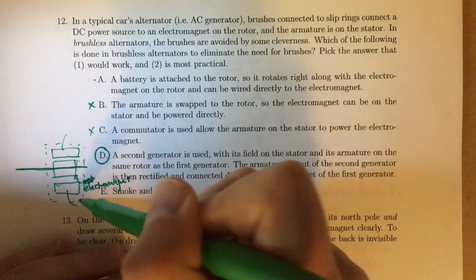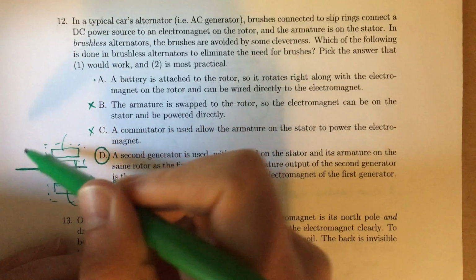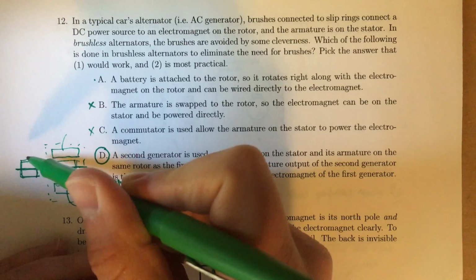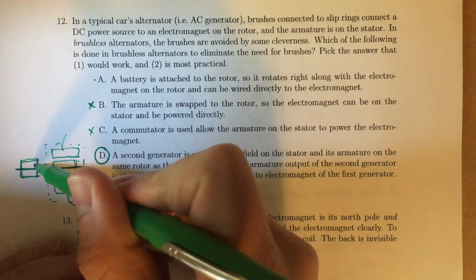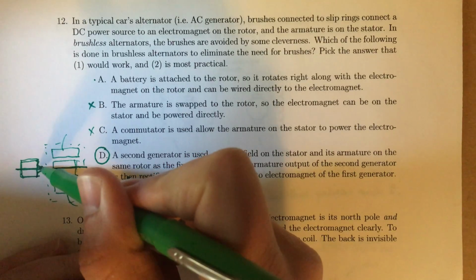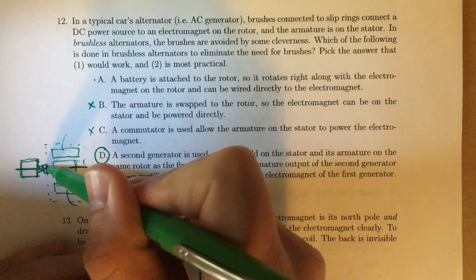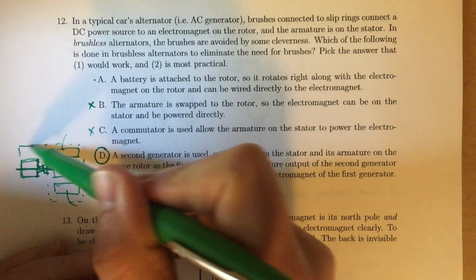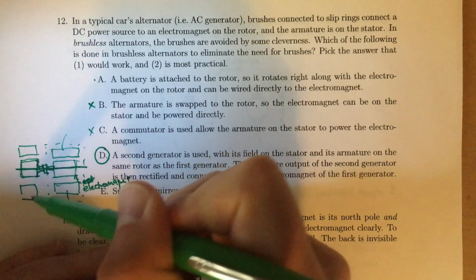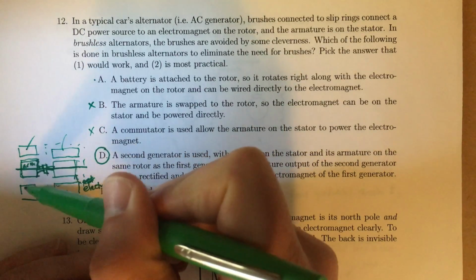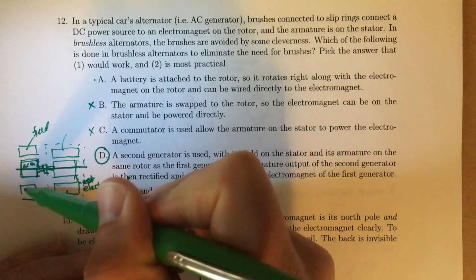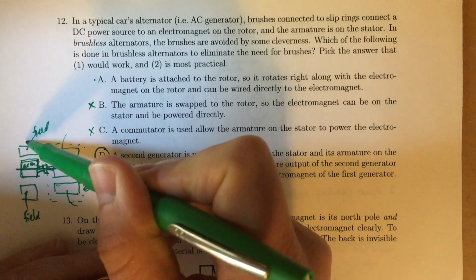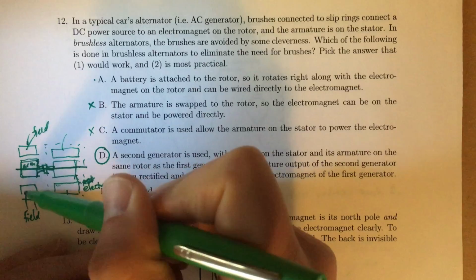Okay, so the second generator, well, it has its armature. So the coils where we're inducing the voltage on the rotor instead. And so we can just take the wires from the end of those coils, run them right down here. We'd need to put them through a little rectifier or something like that and hook them up to the electromagnet so we get DC power to the electromagnet. And then we can have, so this would be armature, this would be field, and the field, because they're on the stator here, you can just wire them up directly to some DC power supply to get your field in there.